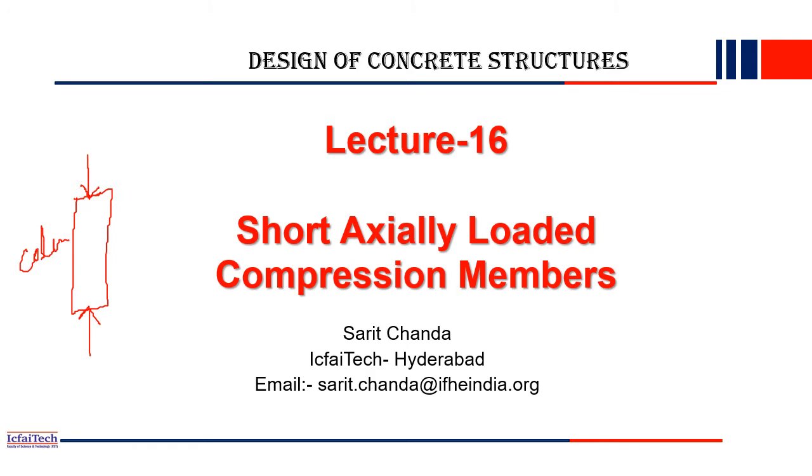If a load is acting transversely about the axis of the member, if any load is acting perpendicular to the axis, then we call this a beam. Although both the members are vertical in nature, still this is a beam because here loads are applied in a transverse direction, whereas in this figure it is a column because here the loads are acting in a compression manner.